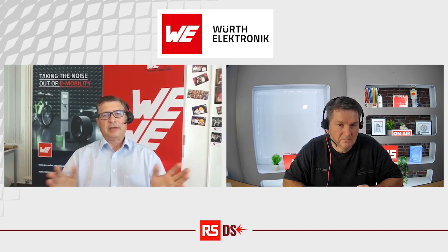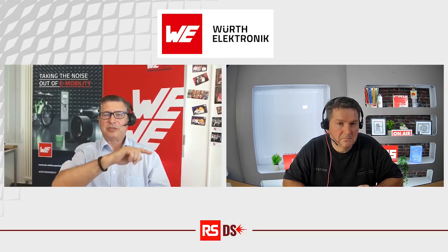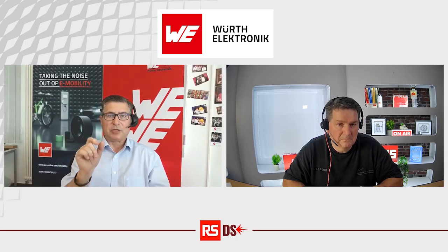And like I said, LT-Spice is the best and the cheapest way, because you don't have to pay any license. You can use it for commercial work, you can use it everywhere, and you can make a nice simulation and see the behavior, how this filter affects. It is just changing some components, or instead of using just an inductor, you can use a chip bead ferrite, which is much more effective and has a low Q factor for not ringing and so on.